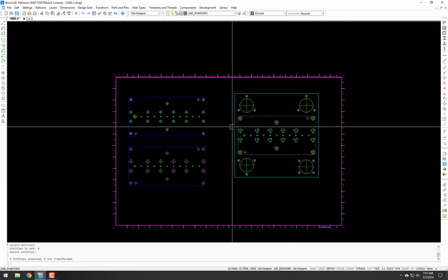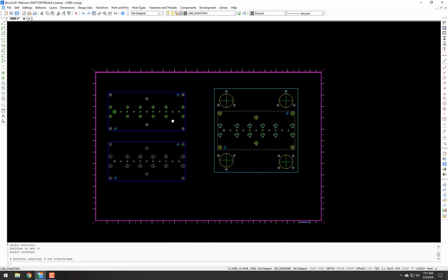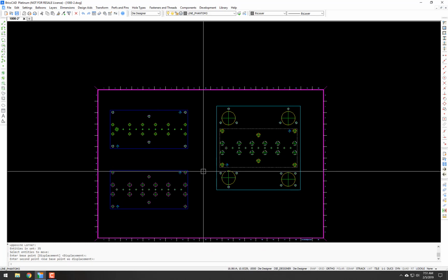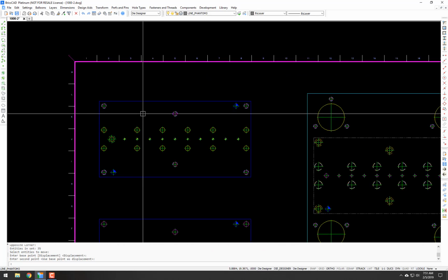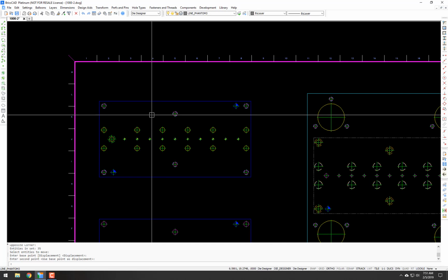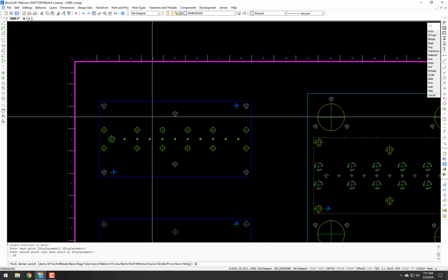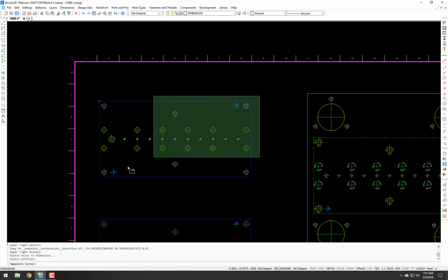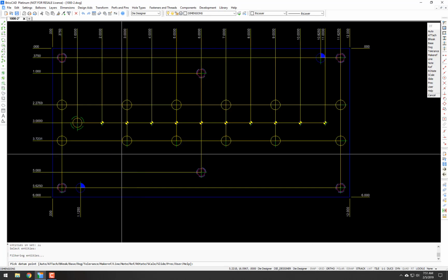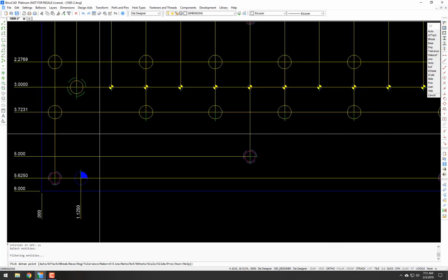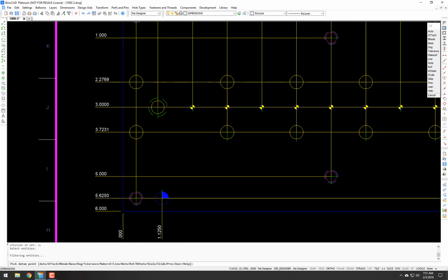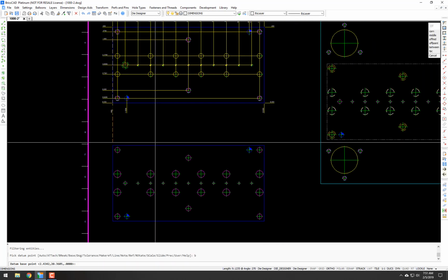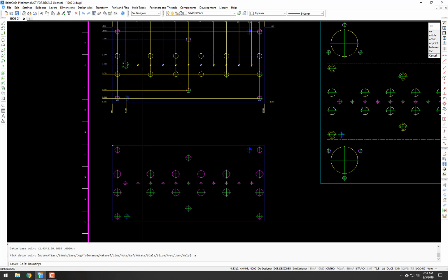I'm not showing a side view in this case, just to speed things up a little bit. Like I said, this is a longer video. But anyways, I'm going to dimension it. I'm going to hole chart it, and so DT base point upper left automatic. Boom, it's dimensioned. 4 places on like dowel holes, precision holes, only 3 places on like tapped holes, base point, auto.